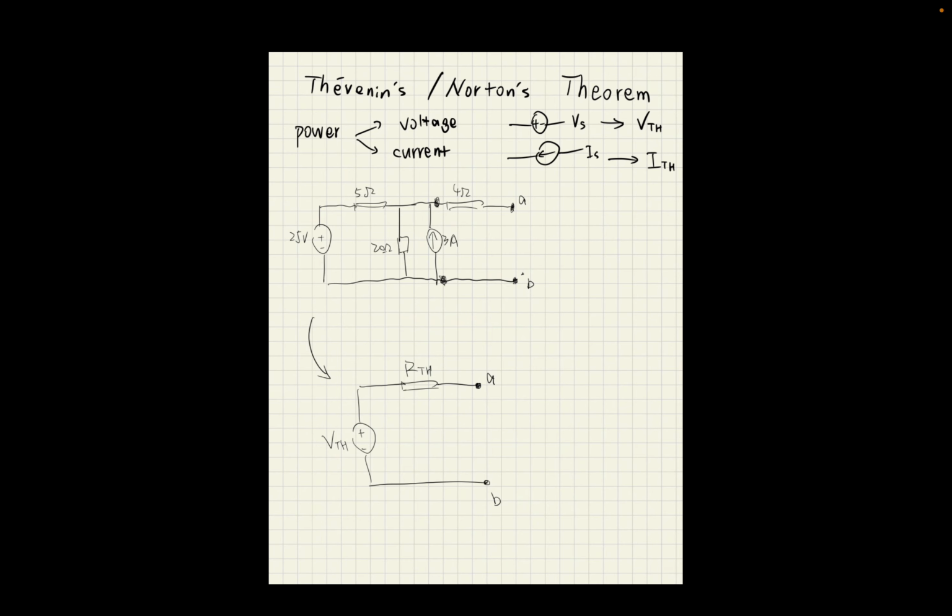So if you want to cancel it, first we have to know what their effects on the circuit are, so that we can cancel it, right? So for an ideal voltage source, of course, the major effect is to provide 25 volts. Okay, so to cancel it, we just erase it. We don't want this part to contribute any voltage. So no 25 volts, nothing.